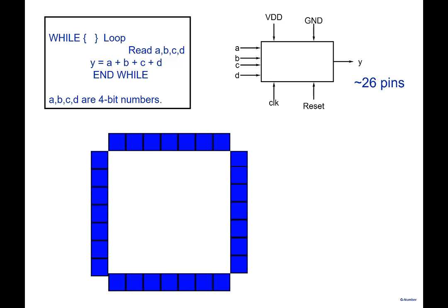All right? Now, as I said, finally, this IC is going to be implemented on a piece of silicon. And this is where our IC is going to be. All the gates and all that you've seen, registers, controllers, everything would be here. And what you see here is that it's surrounded by what we call pads. These are big pieces of metal deposited on silicon dioxide. The dimension of these pads, they vary.